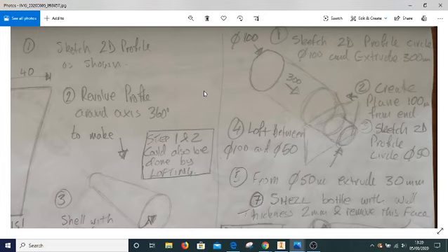Step number 2, I've said that on the end of that extrusion I'm going to create a plane which is 100mm from the end of it, so I'm creating an offset plane from the end of that extrusion, and on that plane I'm going to create a sketch, a 2D profile with a circle of diameter 50. Now what I should have said here, and I've omitted it just to show that we all make mistakes, is that that circle has to be concentric with the larger cylinder so that it ends up in the centre and we have a resulting symmetrical shape.